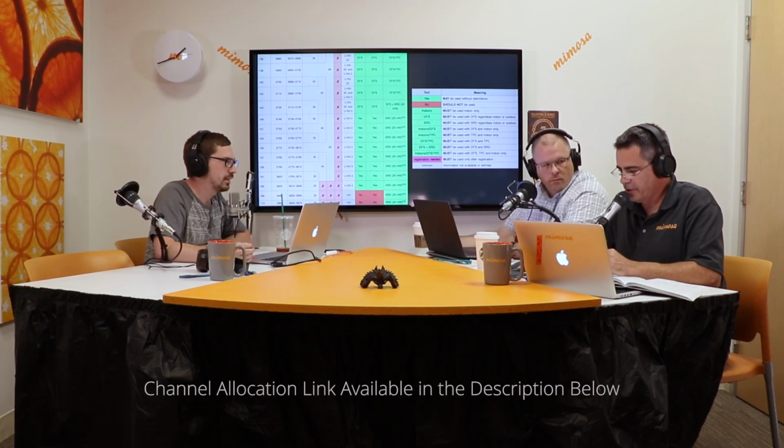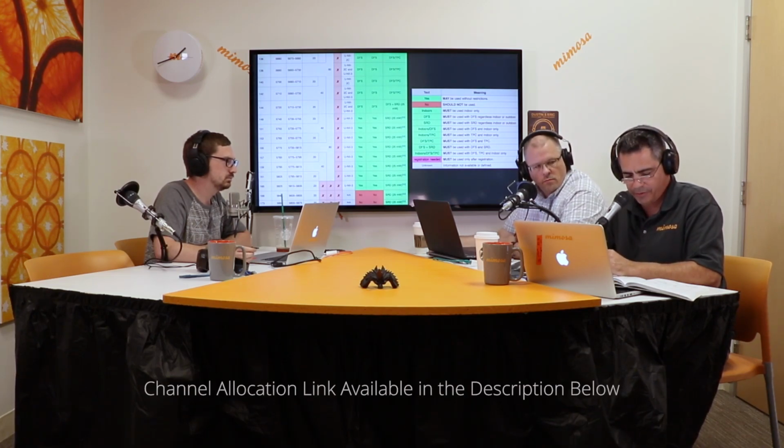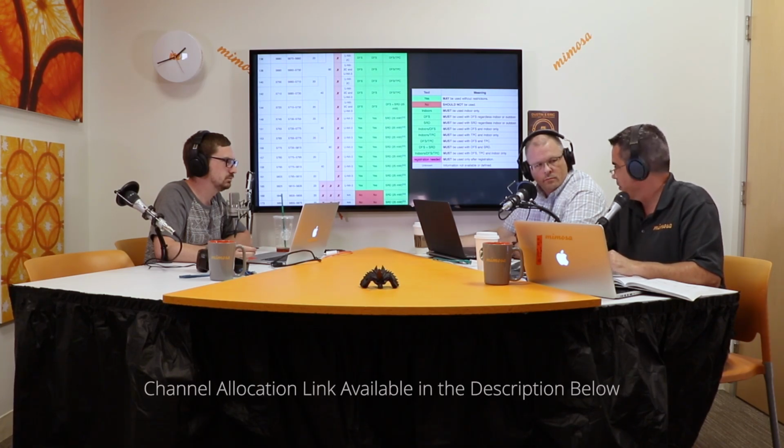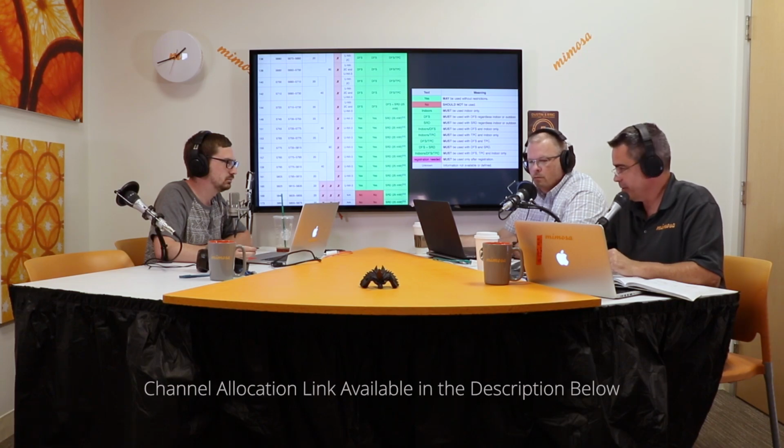How about the folks trying to move up in frequency, try to get to, say, 6,200 or 6,400 with some of the radios? They want to get out, they want to go higher, but they're using the same antennas that maybe have a slope or limited frequency operating. That might cut off at 5,900, but they like to push it up and go to 6,400 with it.